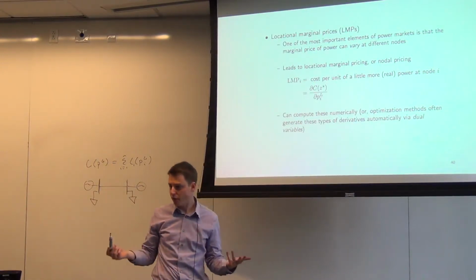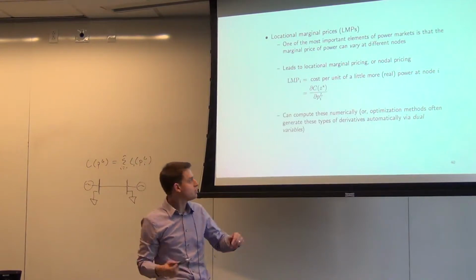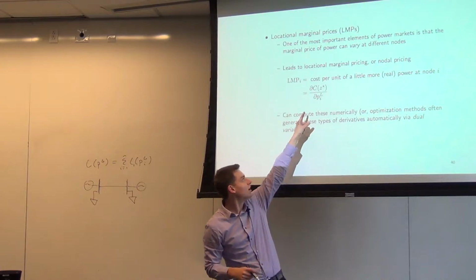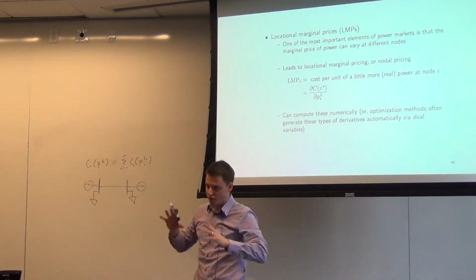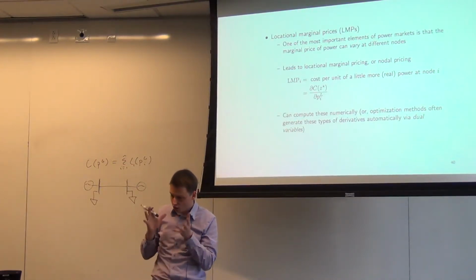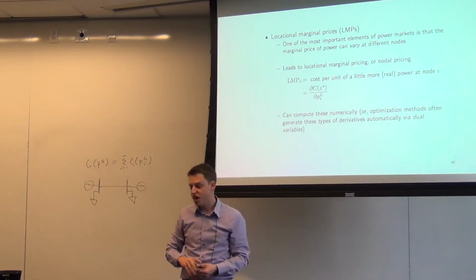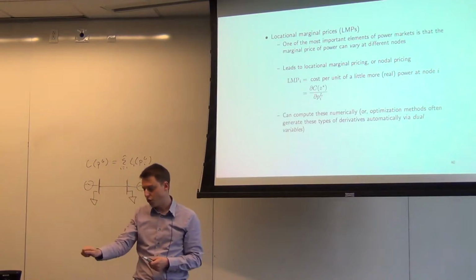That is the output of power flow. So this is not equal to the derivative, for example, of the cost C_i. It's the derivative of the total cost, the total cost of the entire system when you solve power flow, if I change the load at node I a little bit.